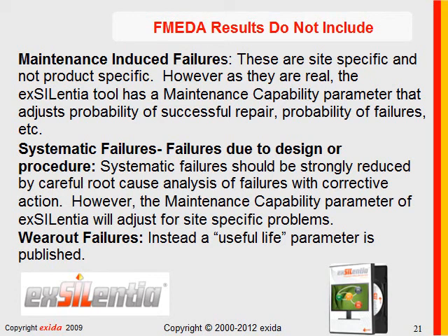Systematic failures are not included. Many field failure data studies include failures due to faulty designs or faulty maintenance procedures. And it is very important that those failure records be recorded so that improvements can be made, corrective action can be made. Secondly, wear-out failures are not included in an FMEDA.